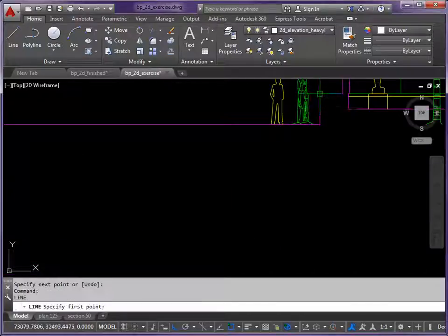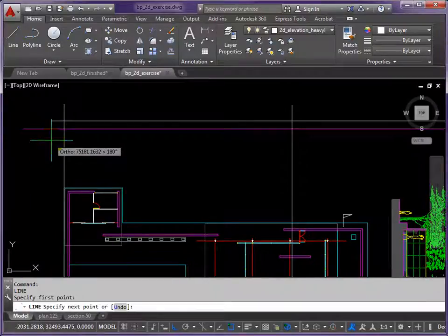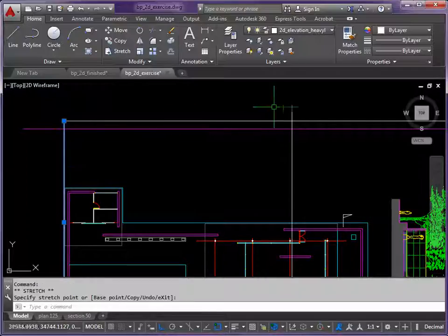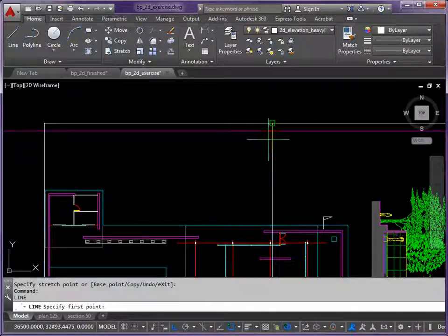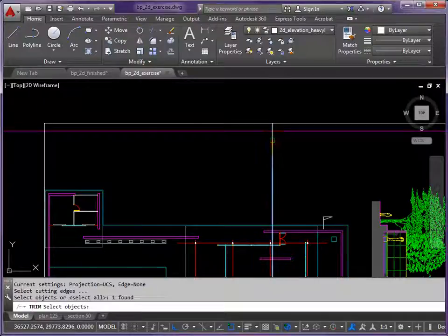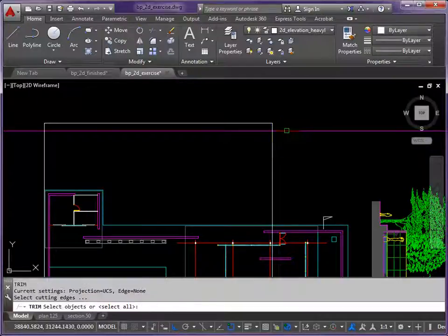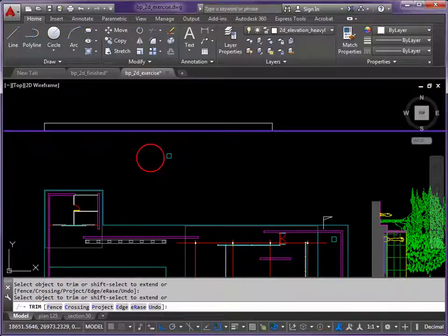Then bring a line across from the section. So this is, we're drawing the plinth. Okay, you can take that perpendicular if you want. Now you can use grips if you wish, or you can use trim or fillet, whichever is easiest. TR, return. Pick the cutter, return, chop, return twice to bring back the command. Pick this as the cutter and return, and chop, chop.